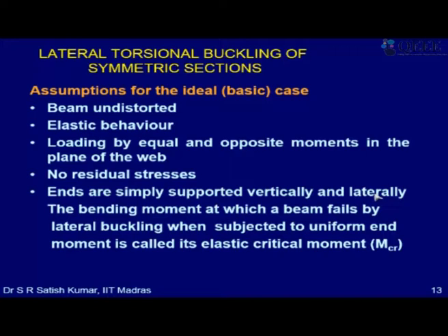But now I'm worried about buckling in plan. So I want to know what constitutes a simple support in plan. It will look something like you put two fingers and put your hand in between. Now you can rotate your hand without moving like this, right? These fingers are not allowing this support to move this way, but they are allowing free rotation. So that is a simple support in plan.